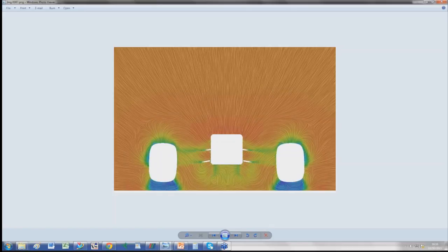So it sort of stopped, and actually you can see it went up at the end. It's quite weak, so it will be dragged a bit, and it's sort of hitting the suspension leg at the back. Believe me, on a developed car, it doesn't work this way. It stays in this area much stronger. So what I mean by that is, at the moment, we've only done about 10 iterations on the car. So we have designed the car based on experience, and then we just do one change at a time, trying